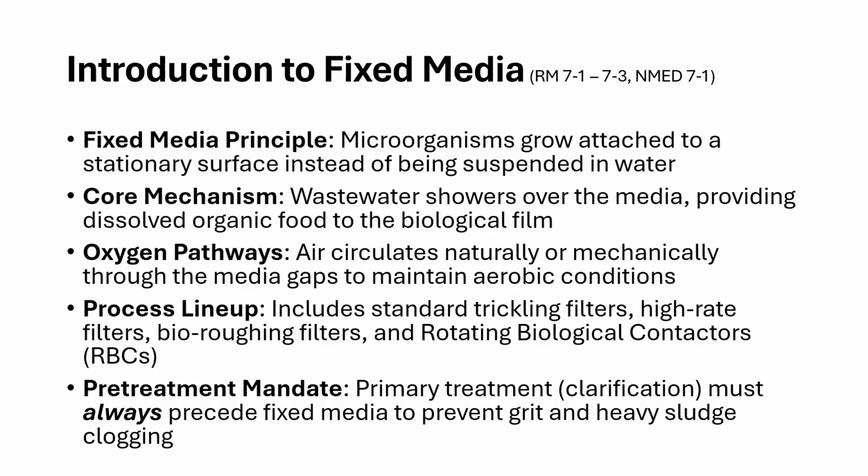So the film is attached to rock or other filter media in a trickling filter, and we trickle the wastewater and the organic load in that wastewater over that media that has the slime layer attached to it, and that's how those microbes metabolize or chomp away at that waste.